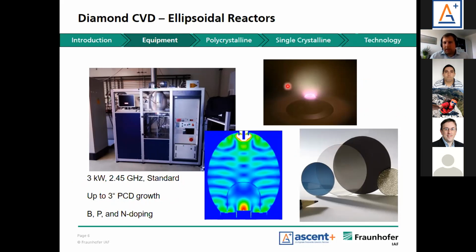On the inside, when the plasma is ignited, here is a single crystal diamond that is further overgrown. Then you see the plasma on top during the process. Also here, again, the different kinds of diamond, boron doped, intrinsic. Then if you have a very high growth rate and a very high amount of methane, you can get dark diamond as well, because you get graphitic impurities. And on the right hand side is unpolished polycrystalline material.